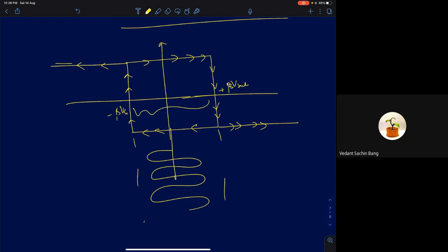Vsat and plus beta Vsat, there are two possible states. It can either be plus Vsat or it can be minus Vsat. And that depends upon the initial condition or the previous state. What was it before? Okay. So therefore, your input should be greater for your Schmitt trigger to switch.